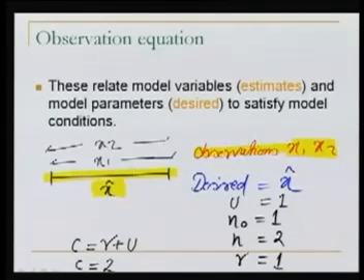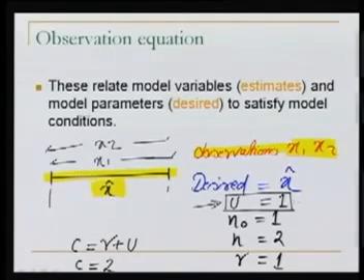Now u here stands for the number of unknowns in terms of the desired quantity. The desired quantity here is the length of the line. So here is one unknown. So u is equal to 1, and n is the actual number of observations taken, with the minimum number of observations which can determine this unknown being u. R is the redundancy.